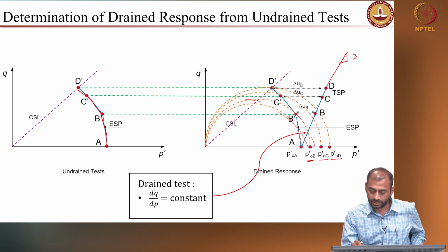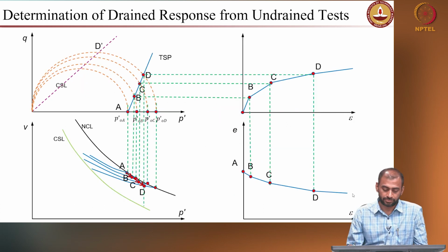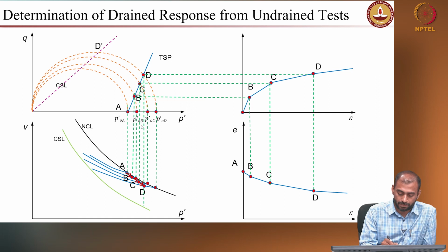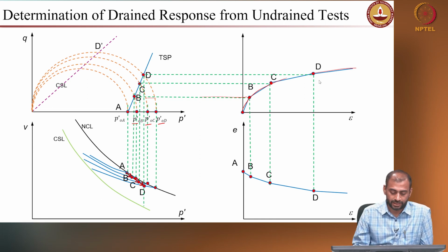the stresses on the undrained state and the total stress will give you the excess pore pressure. So you have the total stress path, you have the effective stress path, and the difference between these two gives you the pore water pressure, and you will also get the new pre-consolidation pressure, right. So you have these new pre-consolidation pressures. From this you can actually draw the stress profile for the drained test. So you already know the undrained behavior, but you are trying to predict the drained response.